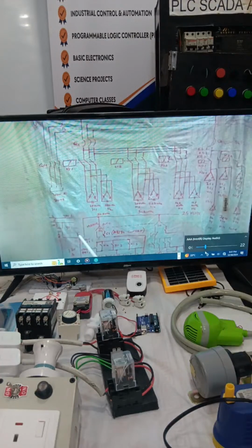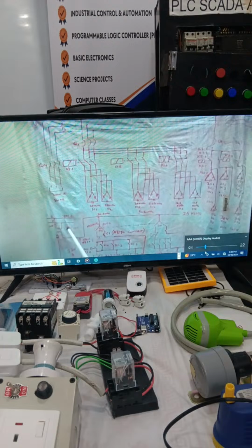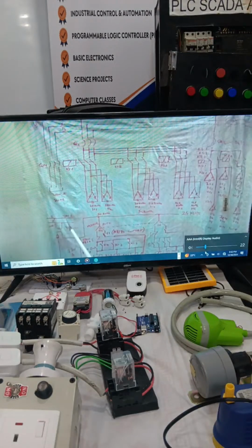But since some components are wired onto the door, like push button pilot lights, this 480 volt cannot be used as a control voltage, because by some accidental contact, if somebody comes in contact with any live parts, they will be severely shocked. So we have to reduce the voltage to a safe limit. Our control voltages are 230, 110, 48, 24, AC or DC, depending on the system requirement.